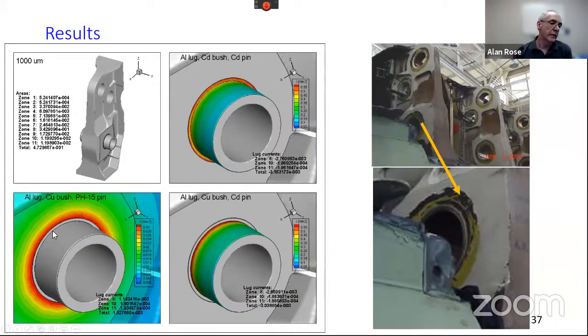And this copper beryllium bushing being so positive has a big impact on the aluminum and starts corroding this aluminum lug intensely. And as you can see over here, very, very nasty, very big, expensive structure. So, knowing how things might proceed from your pristine T0 condition can really help you design that stack up in those materials.